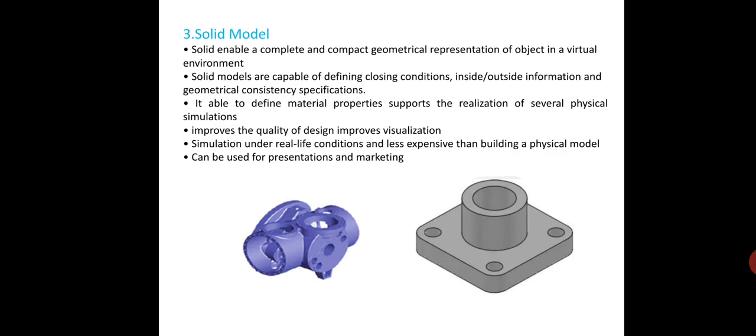Now if you see the weaknesses: models are stored in an unevaluated form, so edges and faces from the combination of the primitives have to be computed when required, with an attendant performance penalty. Smooth combination between two primitives may be difficult or time consuming.